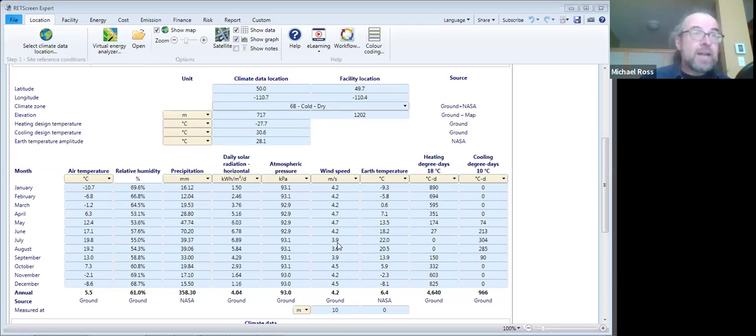It's also not adequate because, as we mentioned earlier, we're about 50 kilometers away from our project location in terms of our climate data. The wind resource varies as a function of location over very short distances due to changes in terrain and roughness and things like that. So for those two reasons, the height and the distance between our climate data location and our project, this wind speed is not going to be sufficient for us. However, the air temperature and the atmospheric pressure don't vary over short distances. So those are going to be useful information that we can use in our analysis.